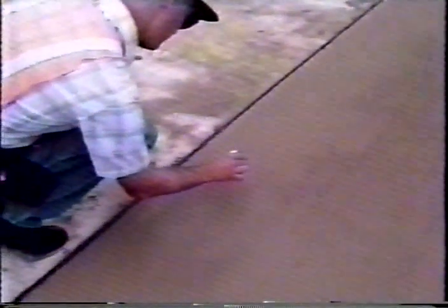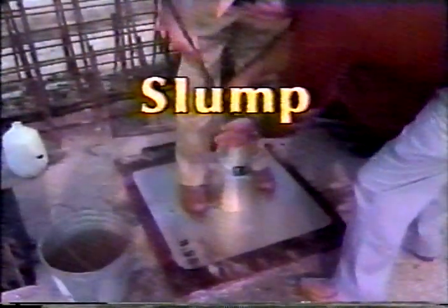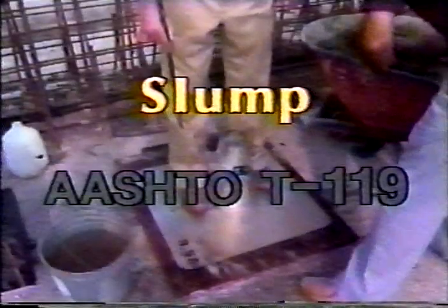The temperature of in-place concrete is measured in the same way. Now, the air temperatures during concrete construction are also important. The high and low air temperatures must be monitored daily. Next on the list is the slump test, AASHTO T119.